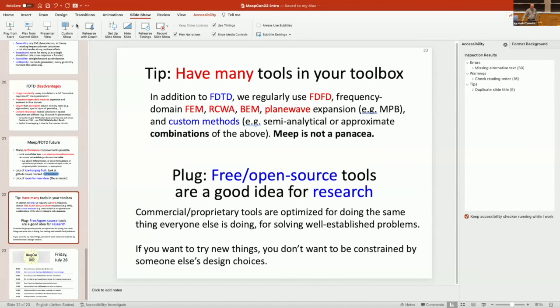The nice thing about computers is that a method like FDTD is not very specific to the geometry. There's nothing in Meep that knows that you're simulating a sphere versus a cube, except for the distribution of dielectric constants. So if it gives the correct results for a sphere, it's pretty likely to give the correct results for a cube. That being said, you also want to test it against other tools. If there are two or three programs that agree on a geometry, that's a good sign that they're working, right?